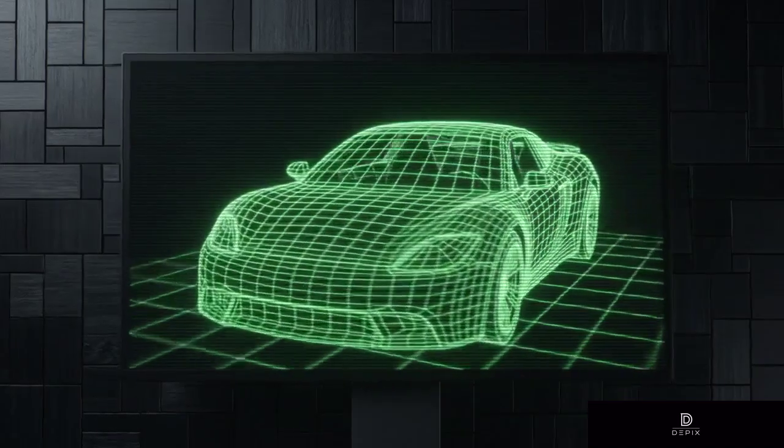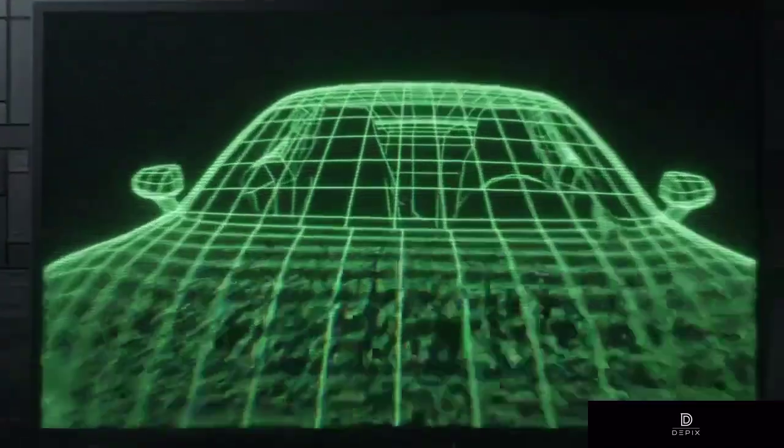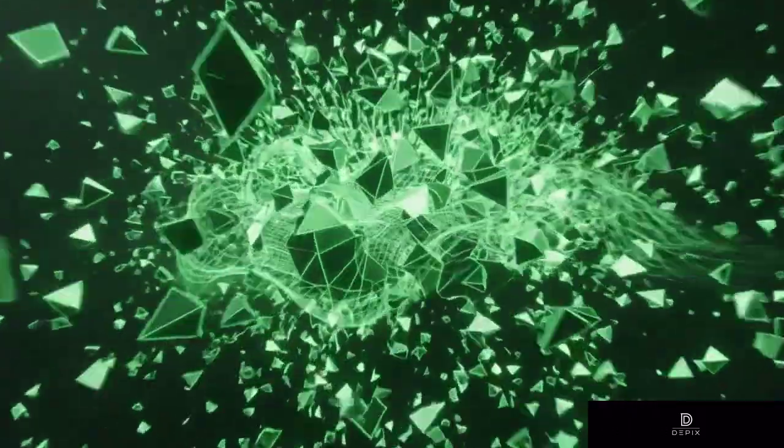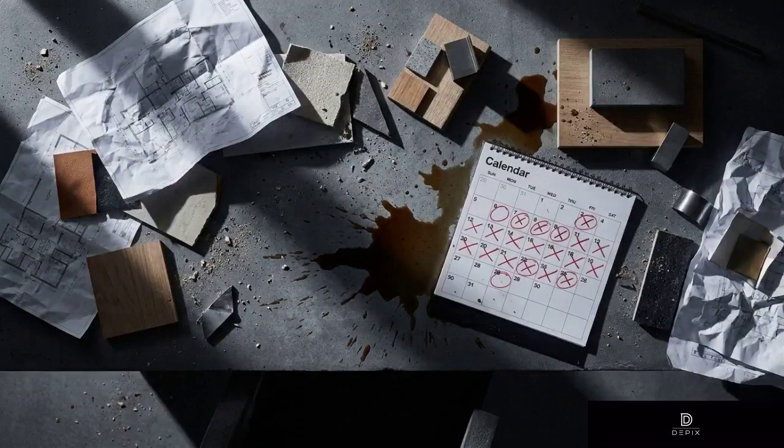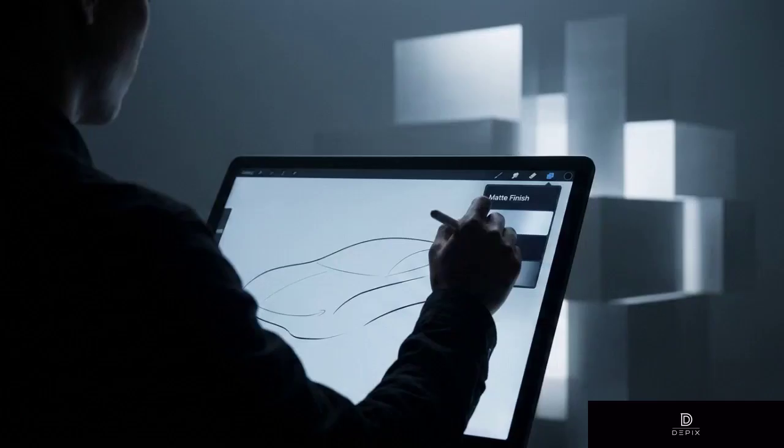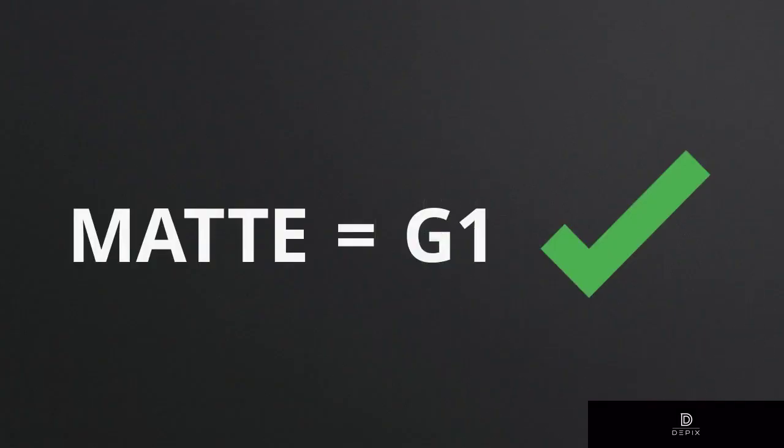The reflex reaction is to demand maximum G3 continuity across the entire product just to play it safe. But calculating that level of geometry everywhere requires immense control and wastes months of pipeline resources. The actual solution is to define the material finish family at the earliest concept phase. Naming the finish establishes the required continuity class up front, before the first digital panel is drawn.